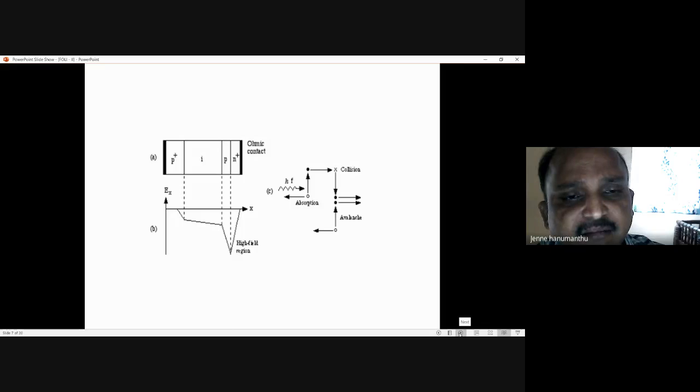But it is not happening in the PIN diode. The PIN diode doesn't have this structure, so you get less current, less conversion of light into electrical signal. But we can get maximum current from the APD because of electron multiplication. It is also called the reach-through effect, because the multiplied electrons reach towards the additional reverse bias junction.